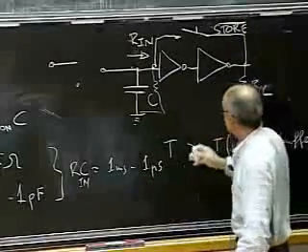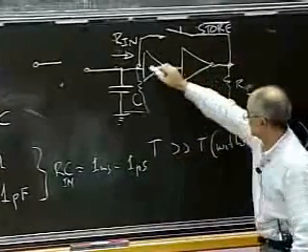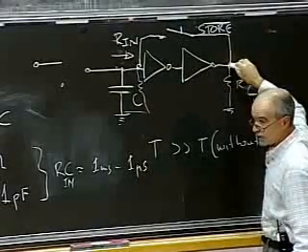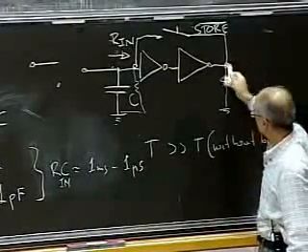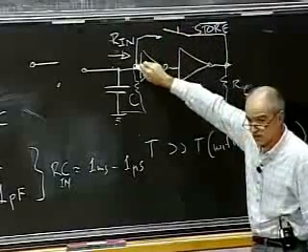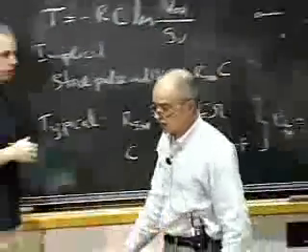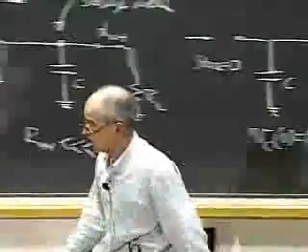Okay, so what I'm doing now is I put a charge here. It produces a valid 1 at this point, and then I'm feeding this valid 1 back to the input. As you can see, this will now allow me, even though I have a high resistance, to store the value for a long time.